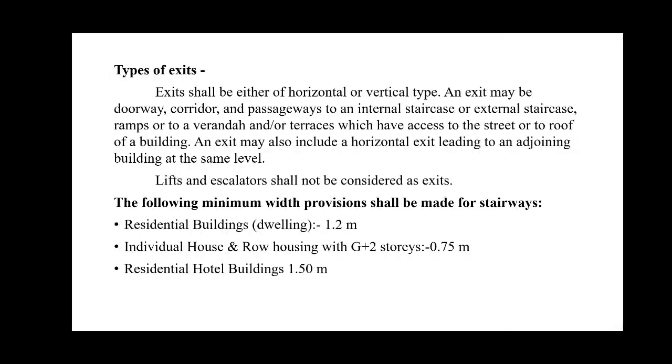and it may be the doorway, corridor, passageways to an internal staircase or an external staircase, ramps or to a veranda or to a terrace which has access to the street or to the roof of a building. An exit may also include horizontal exit leading to an adjoining building at the same level. Lifts and escalators shall not be considered as exits.